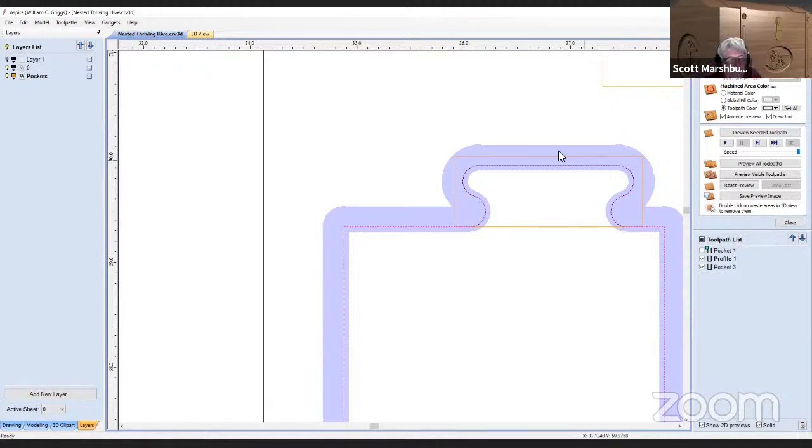Yeah, eCabinets does pretty much the same thing. When you set up a dado in eCabinets, you set up a fit tolerance and a depth tolerance, and it doesn't show it in the drawings. You can't take your tape measure or ruler and see that 3 thousandths or 5 thousandths or whatever it is you added. It doesn't show up. But when it cuts it on the machine, it knows what to do.